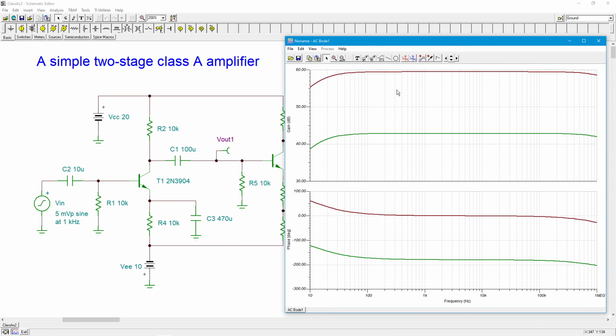All righty. So let's see. Where's our legend? So the gain, let's see, V out stage 1 is the green. We can see that's somewhat over 40 dB, pretty big. The V out number 2, that's sitting up here about 60. So we're getting upper teens for the gain on the second stage in dB, right, versus 40. So that works, generally speaking, what we would expect, right? We expect this because it's not swamped, to have a higher gain than this.